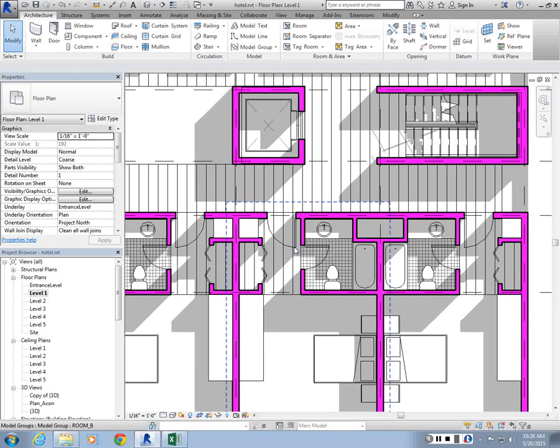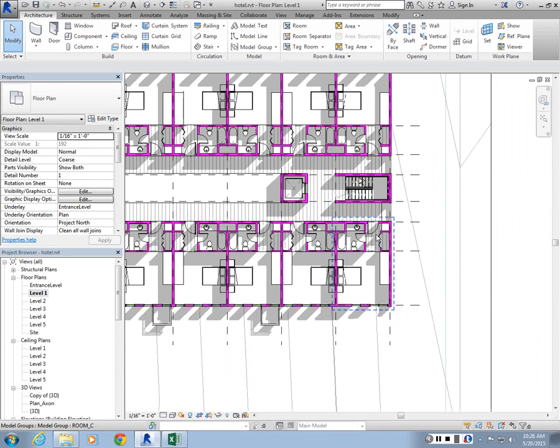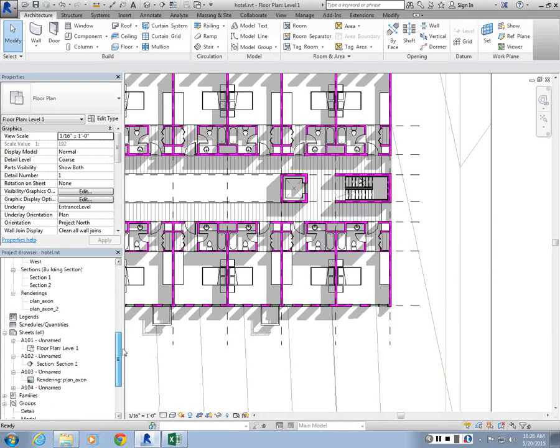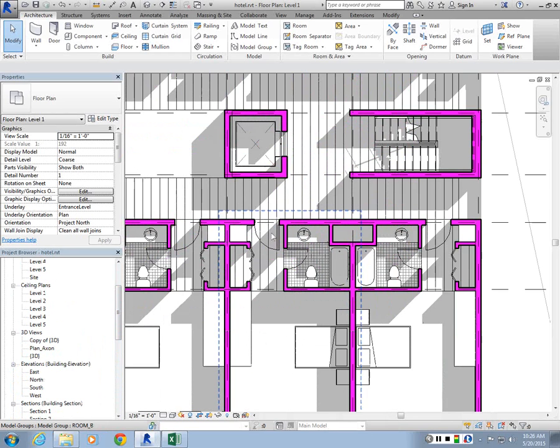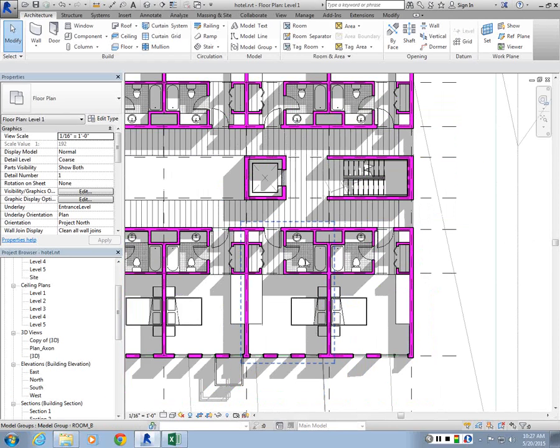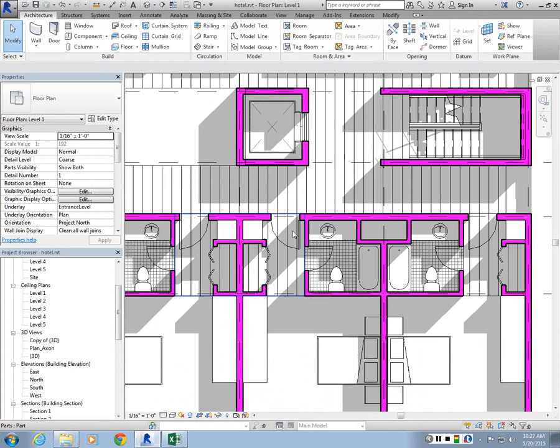Say that again? Like if all the doors were grouped and you wanted to change them by making them something different, can you do it as a group, or do you have to ungroup them and then change the instance? So if I want to change this door that is part of a group, every other group that has that door will be updated as well. Okay? But if this door has been used within this project and it's not part of the group, right? And I'm selecting the door, and I'm overriding the type properties of it, like the material, application, finishes, then all the doors that have that type will be changed as well.